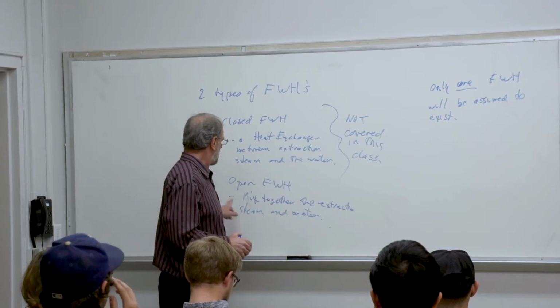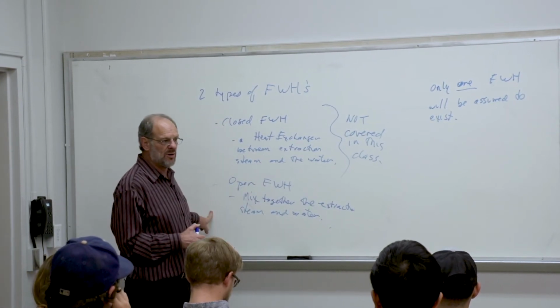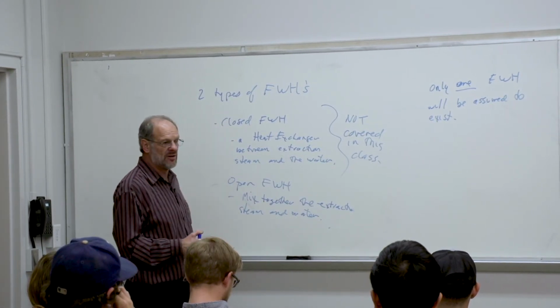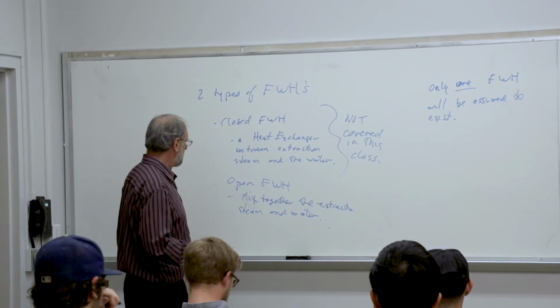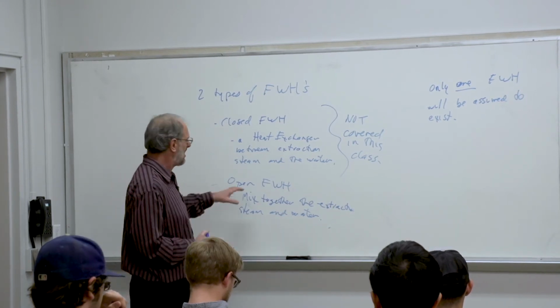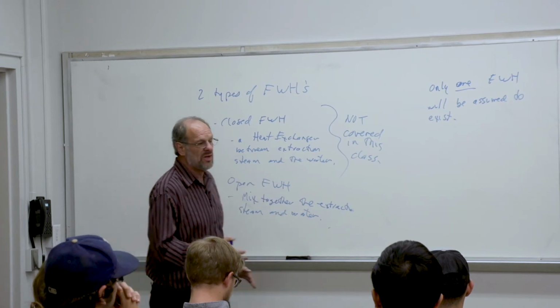I've gone to plenty of power plants where they don't even use the word feed water heater. They just continually call it a deaerator, which is fine. From an operational point of view, that's what they really want. They're concerned about water quality. So the open feed water heater is a deaerator.